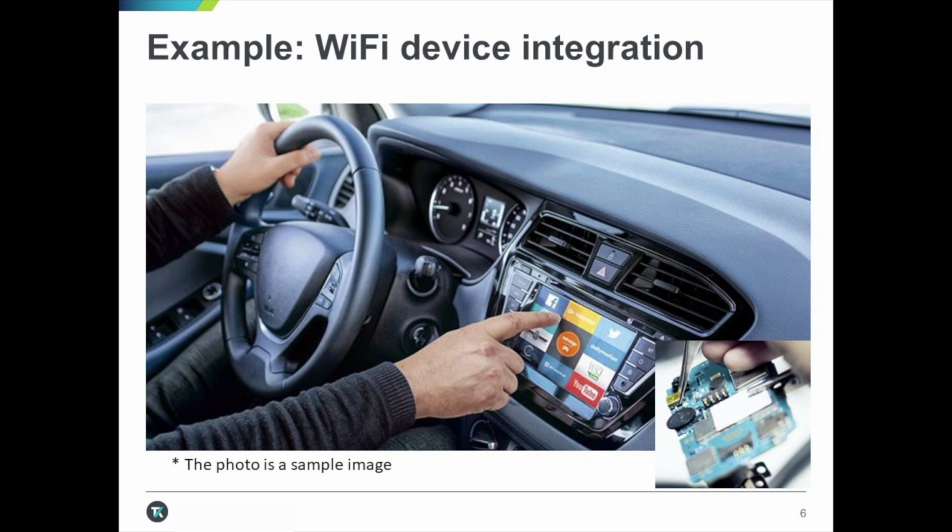One obstacle is the lack of expertise to handle RF testing, leading to some interesting workarounds. I recently had an opportunity to talk to a development team integrating WLAN or Wi-Fi to their automotive infotainment system. They used a pre-certified WLAN module, and the project turned out to be mostly a software project. As the software neared completion, instead of performing true EMI and standards testing, their testing involved looking at Wi-Fi speeds as an engineer moved their device various distances from a store-bought Wi-Fi router. Now, it's possible you could learn something from this, but it's a far cry from true electromagnetic characterization and optimization.